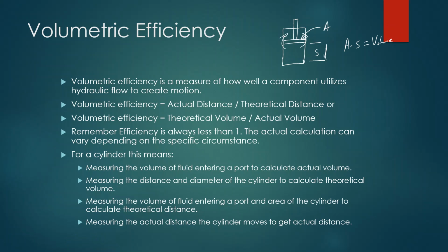Now, on a cylinder, this doesn't happen very much, okay? Volumetric efficiency of a cylinder is great. Absolutely wonderful. Now, what we're going to talk about here in a second is mechanical efficiency, and they're not always great mechanically, but they are definitely very good volumetrically. But pumps can have low volumetric efficiencies, especially something like a gear pump.